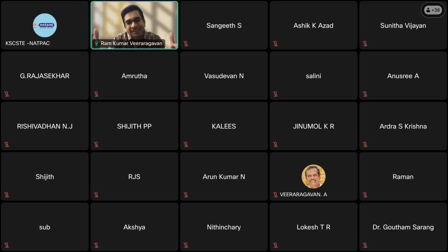So for cracking, for example, there are right now 15 different cracking tests in the market. So there are wide options, but you have to see which are the practical tests that can be implemented for quality control and acceptance methods. When you're looking at that practical aspect with minimal cost and a minimum amount of training required, that would be IDEAL-CT and IDEAL-RT, which are more practical and more easily implementable.